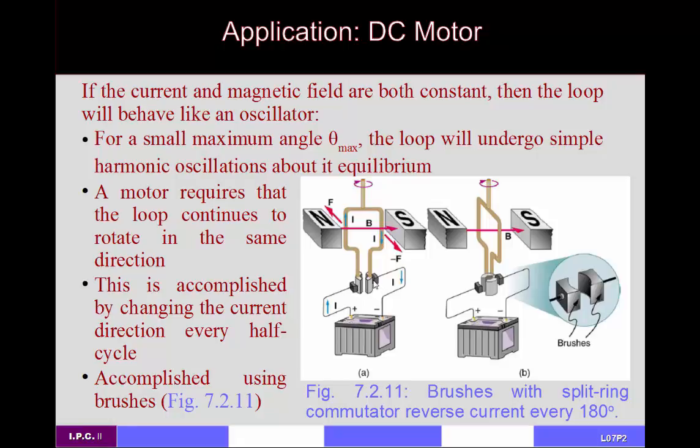So this one gets a positive charge, this one gets a negative charge, and so the current will flow around like this through the loop. This part right here is the actual motor part that's doing work. For example, you could attach a paddle to it, and the paddle would be doing some work, or you could attach a series of gears. In any case, as this thing makes half of a revolution, this coupler and this coupler will cease to contact the brushes.